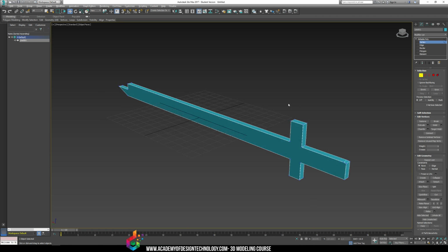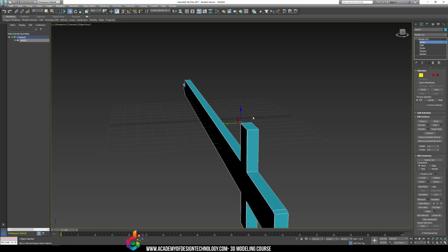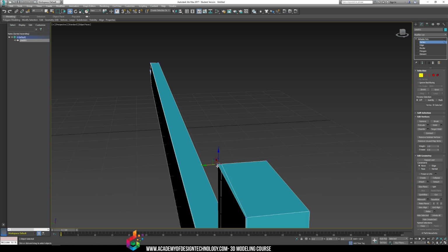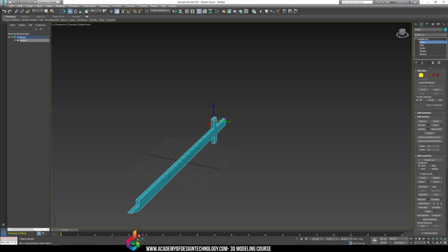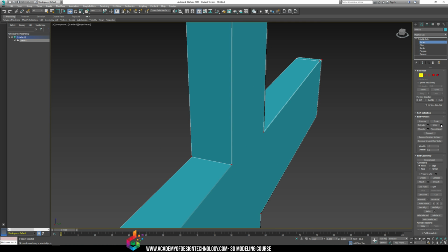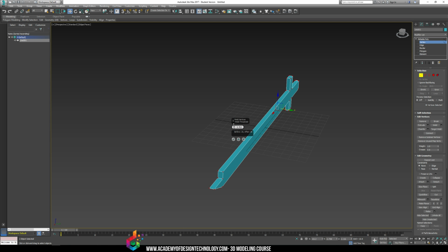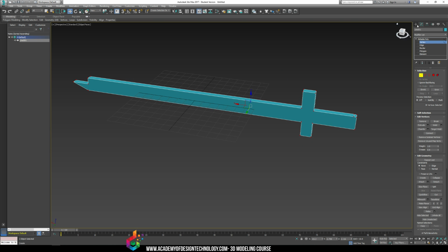We just need to weld those vertices together. Because those new vertices we made on this side, you can see they're still just hanging around. If you want a quick way to weld a whole bunch of vertices that you know are really close together, select all the vertices in your model, go to weld options, and turn the number just slightly higher than normal. And you could see I went from 45 before, after 30, I push apply and continue, and all the vertices that I have that are really, really close are all welded together. And I can tell just by the number increase, like how far apart the other vertices are, that all the vertices I wanted welded are now welded. And now I have at least a prototype sword.